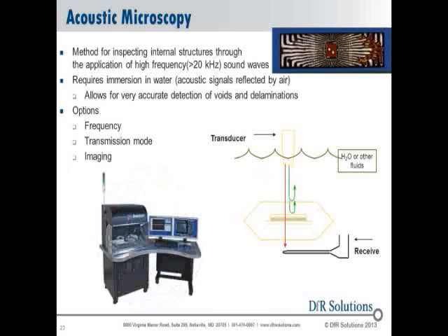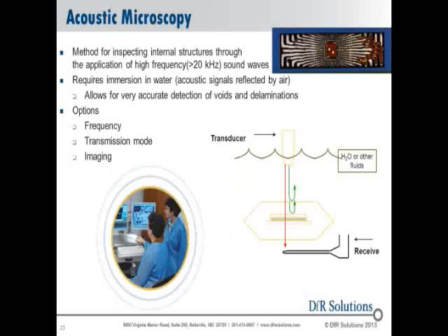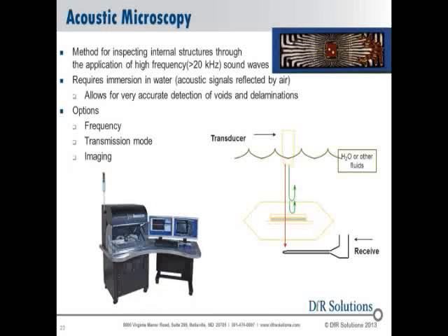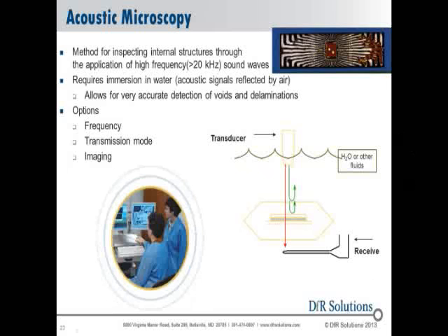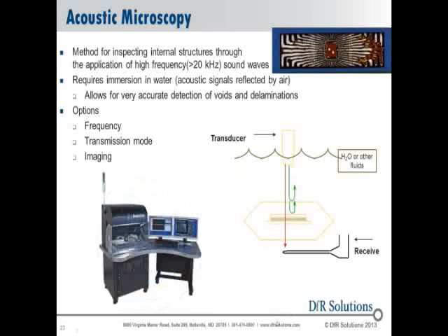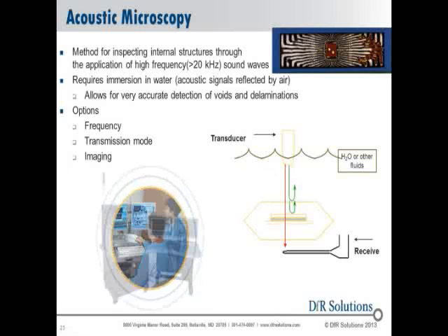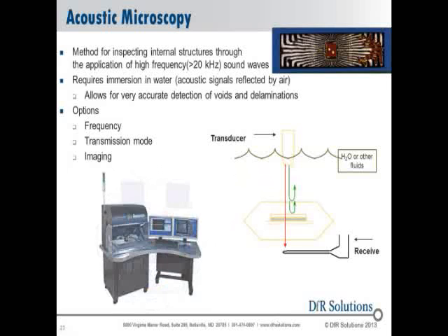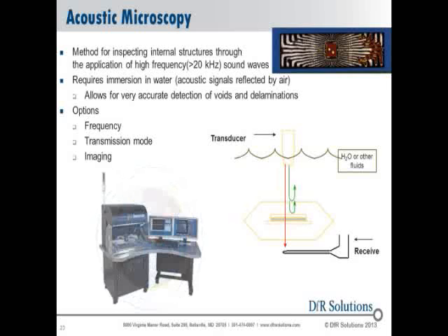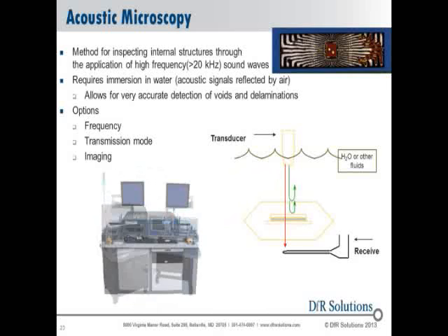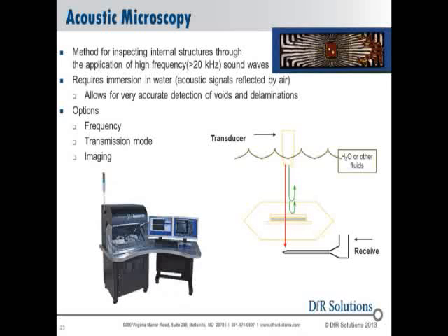We need to submerge the electronic device in pure water, not tap water, but DI water solution, and we inject a sonic wave into it, and we've got one receiver that's looking for bounce back signals and another that's looking for pass-through signals. And what we're seeing here is what parts of the device are well structured and what parts might be loose or have some form of delamination or voids or air pockets and things of that nature, by the way these high frequency sonic signals are absorbed or bounced back.